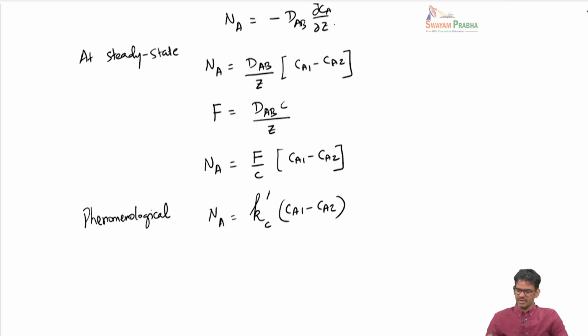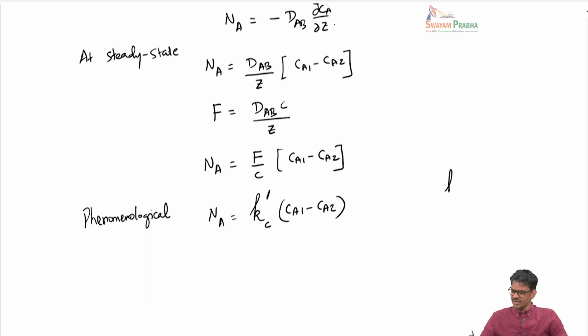Here I am using this prime to denote equimolar counter diffusion. Again, we are talking about differences in the K-type mass transfer coefficient under different diffusion conditions. When you are looking at diffusion of A through non-diffusing B, we simply use Kc. In the case of equimolar counter diffusion, we write Kc with a prime. So, Kc and Kc prime are different things. This is for equimolar counter diffusion.